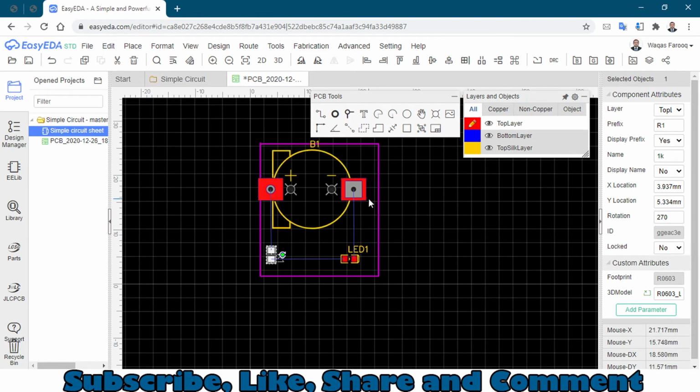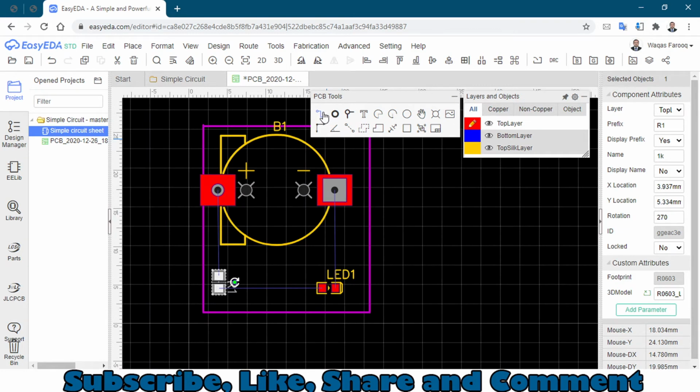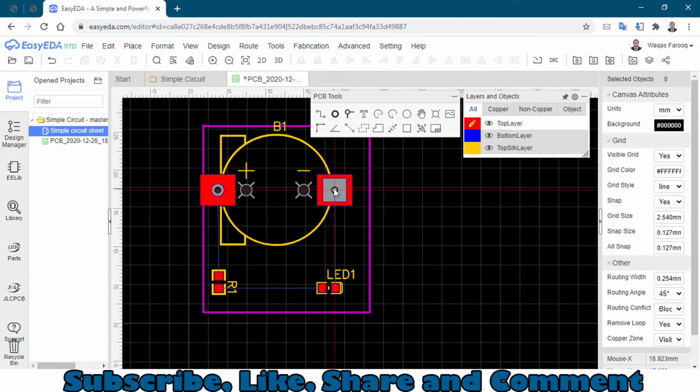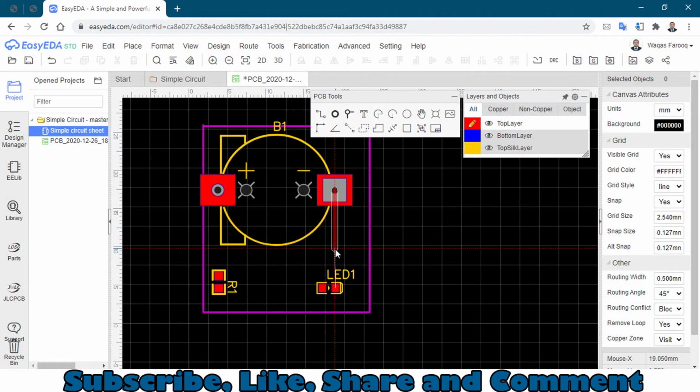To move on, we will connect this component with wire. So we have to select the wire. This is the wire or track. Click on it, and you can also change the width of this wire by pressing the tab button. As we are drawing it, click on tab, and here we can change its width. I will change it to 0.500 mm. Okay, now the thickness of this wire is changed. I will connect here with the battery, and I will draw again right here, and from here on to this LED. So this is the wire that we have on the top layer.